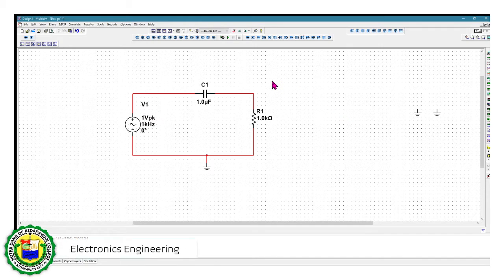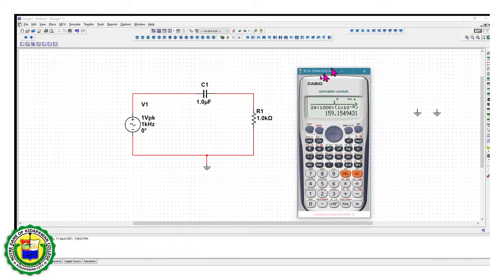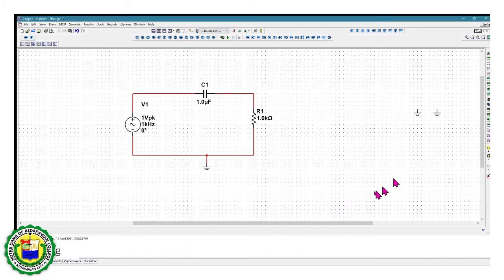So for example, if we are dealing with, let's say, 1 volt of magnitude, or let's say for example if we are dealing with 0 dB of magnitude for the normal frequencies that would be allowed in this particular circuit, then we would expect a drop up to negative 3 decibels at 159 hertz. So let's go ahead and use our Bode plotter.